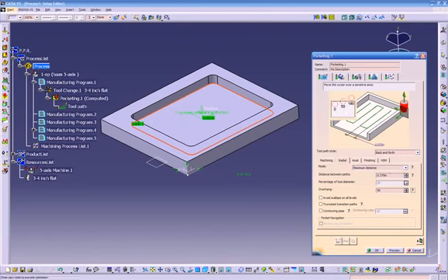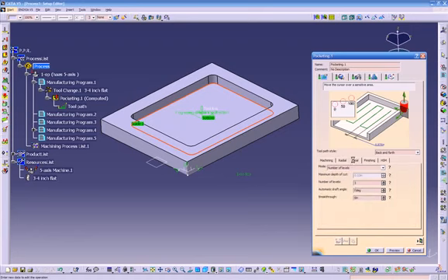It shows you right here the difference. But I like ratio the best, 50% of the tool. Then we have radial, which goes sideways, as you see. Axial goes up and down. So it's asking us how many depth of cuts we want. So just click on this and it will tell you 1, 2, 3, 4.